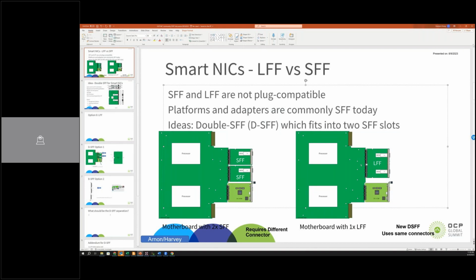Yes, Arnold. Go ahead. So I just want to continue the same thought process. Today when we have customers that want to use 32 lanes, they have to go to a CEM card, but the CEM card is also by 16. But what we have is like an expansion auxiliary connection to another auxiliary card which is plugged into another adjacent slot, or you can theoretically connect it to the riser or to the motherboard, or whatever, either internal cabling. But it's also not standard.